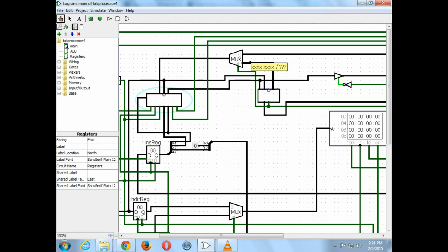And then the other part is when you look at the two outputs of the register bank. One is this guy here, and it serves as one of the inputs into the ALU. The other one is this guy, which is the other input into the ALU. So this is how we can specify the two inputs into the ALU. They come from possibly up to two registers. So the ALU performs the calculation, and then we decide which one we want to spit out.